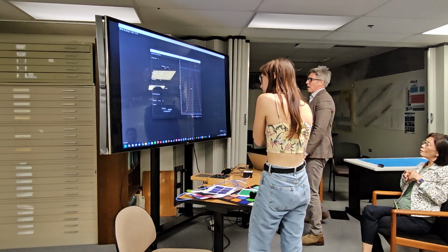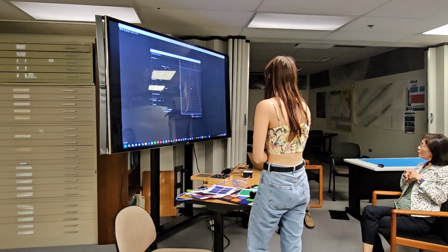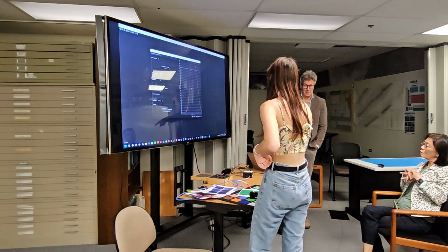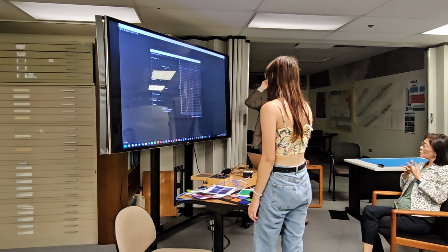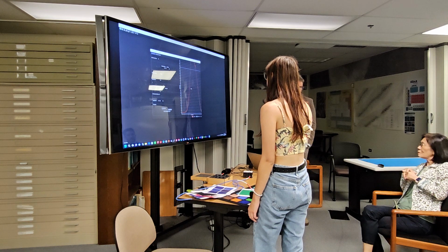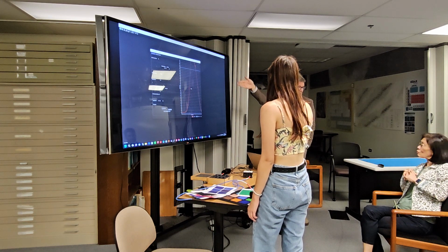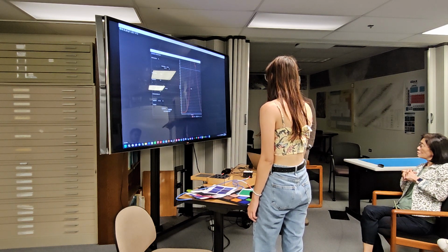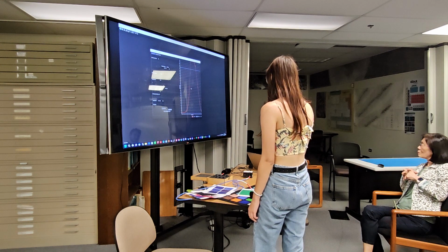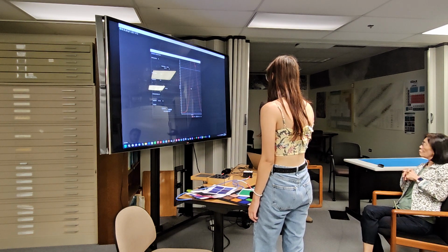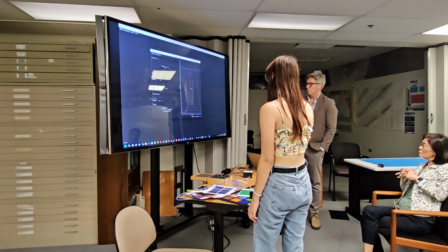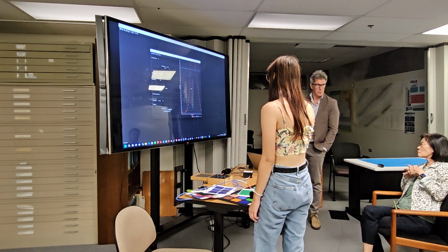So this is now telling me how much light that target is reflecting, and the lamp isn't changing. What do we notice about that signature? Saturating, right? I'm saturating because too much light is coming into the spectrometer from that target. So how am I going to solve this problem? Integration time. This has an automatic way of doing it.